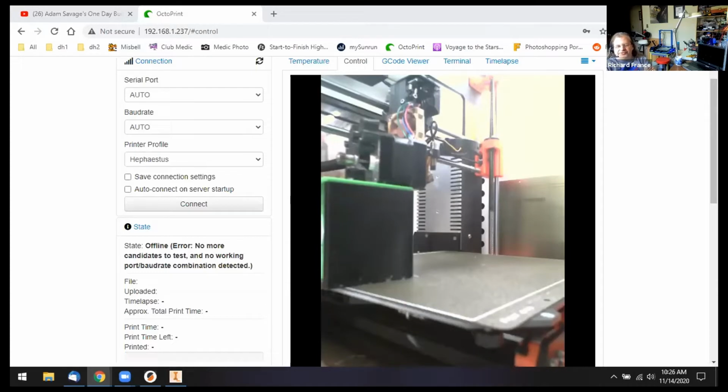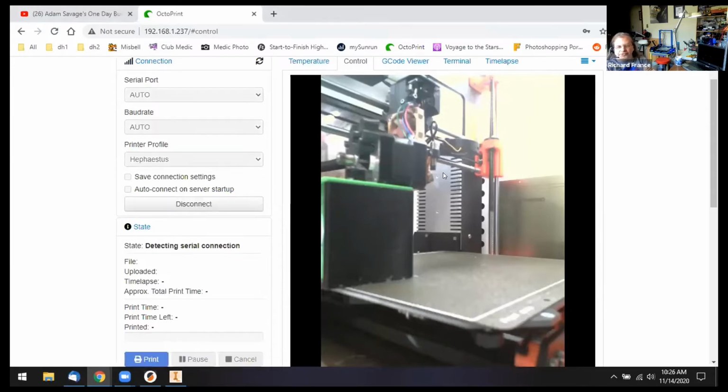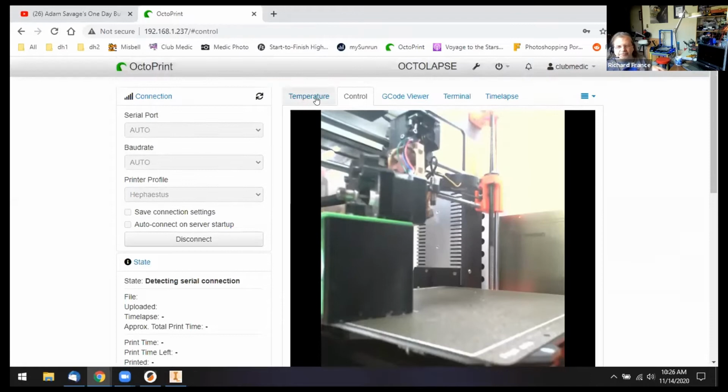For anybody listening who has not done a 3D print before, the tried and true method is SneakerNet. You get on your laptop, take the file that Bruce referred to as an STL, and pull it up in your slicer. The slicer turns it into the language the printer can mechanically understand, what we call G code, which has been an industry standard for decades in the world of milling and things like that. You put that onto an SD card or some memory card, plug it into your printer, go to the little screen on your printer and click buttons to select this file and go. And boom, it warms up and starts doing its print.